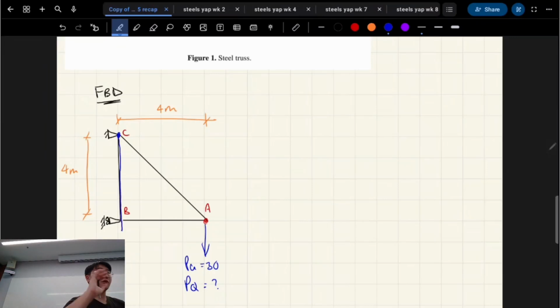Okay, this point's a roller. This thing can roll up and down, right? If there's gravity loads acting on it, it'll probably roll down. I'm going to exaggerate this a bit. So remember, AC is going to elongate because that force wants to pull it down, right?